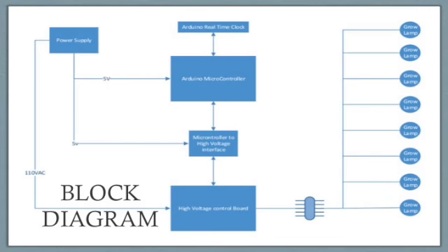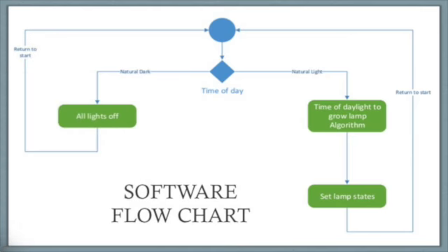The diagram shows how the Arduino microcontroller receives data from a distant weather site. This data is converted into 8 channels of pulse width modulation, or PWM, which is then transferred to the interface module, which uses these pulse width modulation signals to control opto-isolated triac drivers. The triac drivers are connected to triacs, which act as a dampening gate for the 120 volt power supplies for each of 8 incandescent lamps. The lamps are controlled in such a way that simulates the sun cycle for one given day, based on factors such as cloudiness, temperature, and time of year found in the data received from the remote weather site.